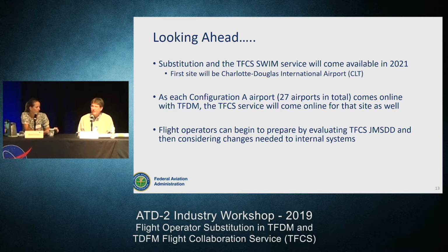Another interesting, just aside, is you'll get TOBTs if you have an APREC or an edict outside of surface metering for what the system thinks you should push back in order to make your time to the runway based on the algorithms of what's going on currently. Right. And those TOBTs are recommended times, so their compliance will not be measured against them.